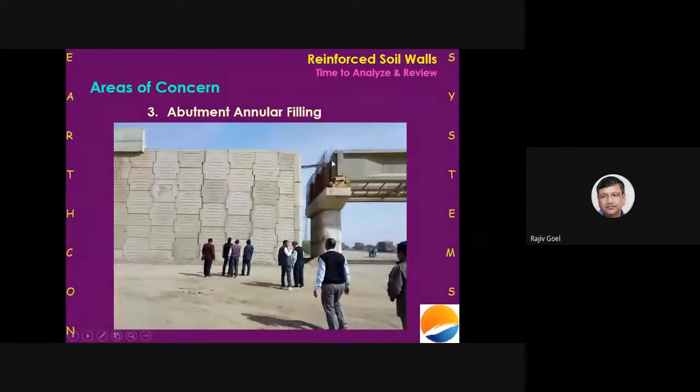Okay, this is another foundation which was done on open footing, and then a lot of investigation went into it, because you can see that this part of the wall has settled and has rotated towards the right, and because of that, the gaps here start to appear. Can we all notice that? From this point onwards, everything seems okay, but this part of the structure, especially over here, these lines have inclined to the right, which means a lot of settlement has happened here.